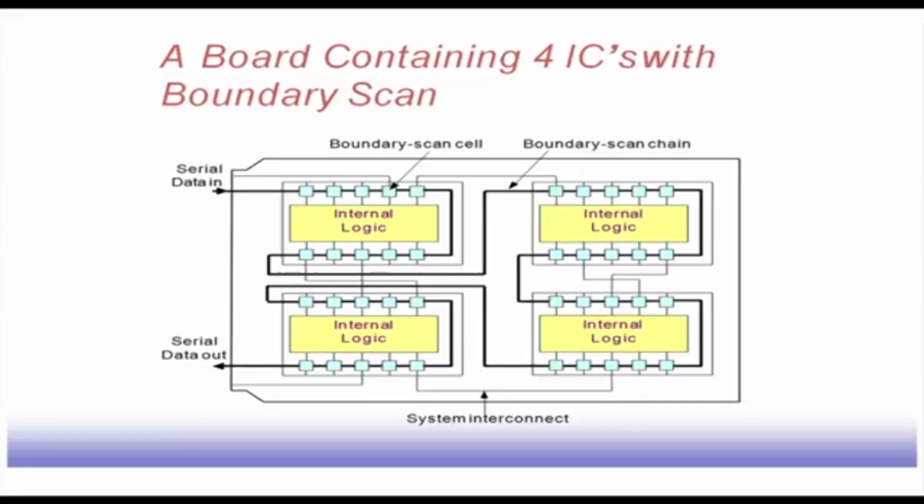So, that is so that I can get a signal propagated through the chip. So, it is very difficult to tell. In logic level, this was possible because the circuit description was known to us, the gate level description was known to us. So, we could use some sort of justification routine, but here I do not know the internal details of these individual chips. So, I cannot do any sort of logic justification there. Okay. So, the only way out is to have some additional chain made like this, so that all these inputs can be accessed.